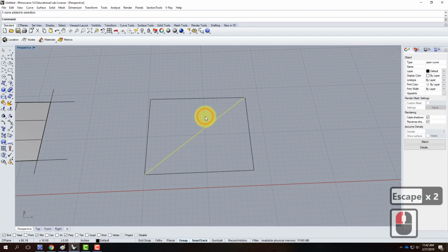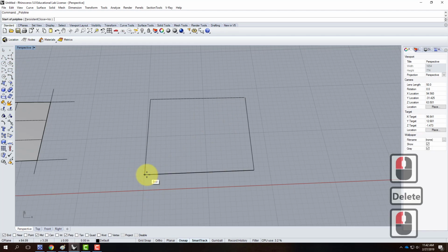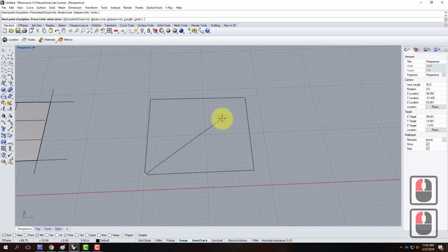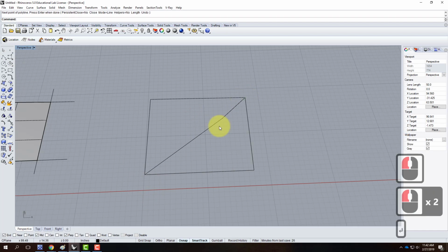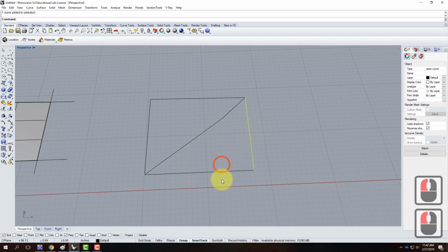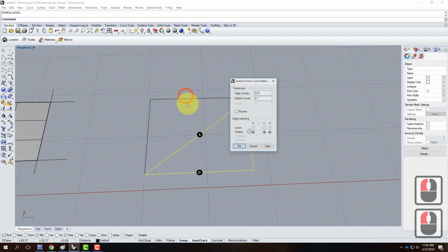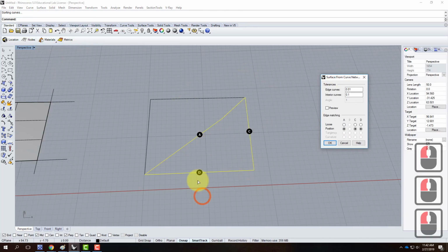So when I'm creating a curve network, I never want to draw a curve that has curvature on it that goes diagonally across to try to build out the surface, unless I build these three together. So I could do those three and do a network surface. Because as weird as this is, there we go, curve network, it still recognizes this diagonal as a direction.